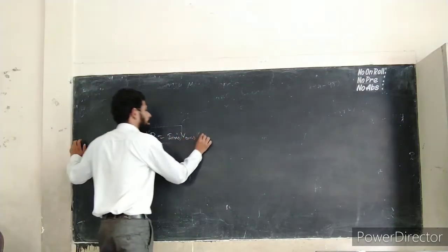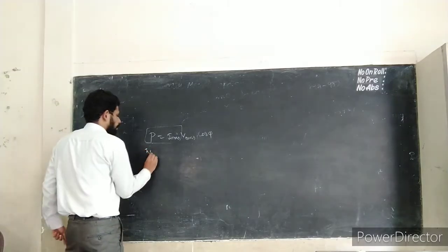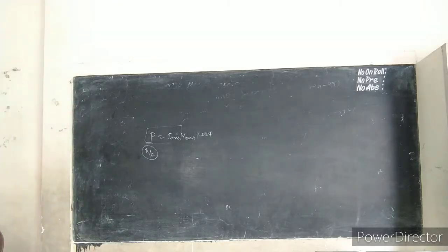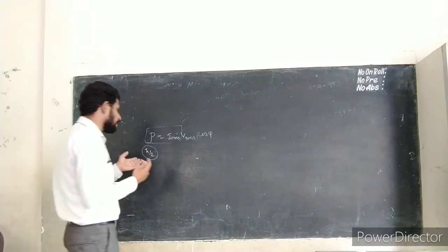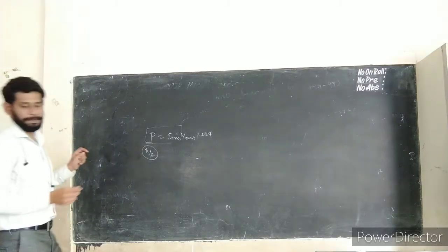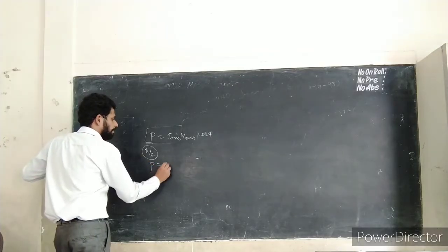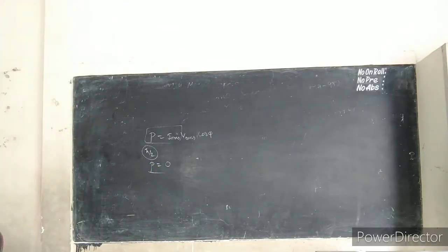This one we call the wattful current. When the other component, Irms sin phi, has a phase angle of pi by 2, where the voltage and current lead or lag behind each other by pi by 2, it is called the reactive component. Then the power consumed by this component will be equal to 0. So this one we know as wattless current.